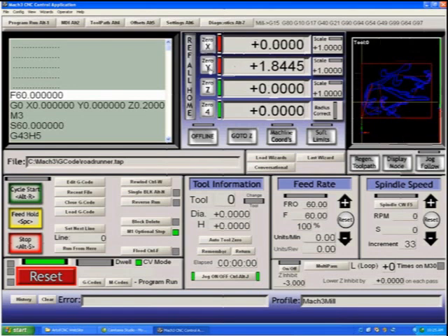If you zero DROs, you can see that those lines moved to the zero point or the origin point of this piece. It's important, though, whenever you zero DROs, that you do a regen of the toolpath so that the system recoordinates the toolpath display with actual coordinate positions.